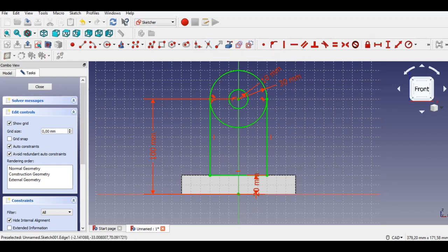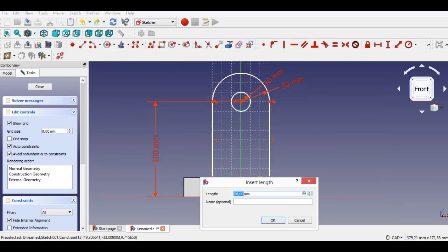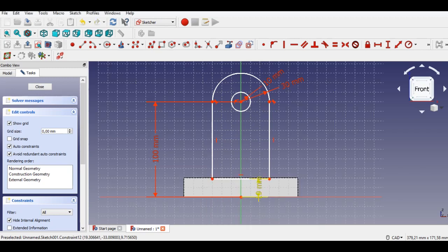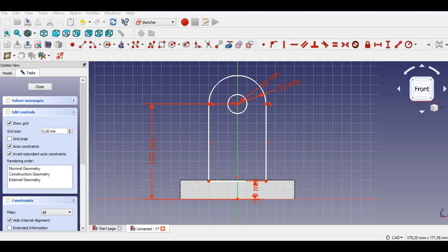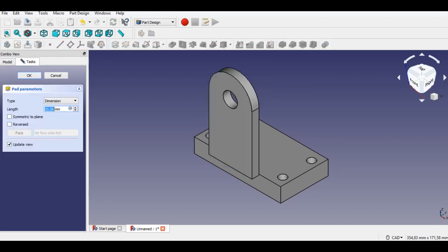We are making a 15 mm pad. We select this pad as reverse direction. Now we return to sketch to make the 3 mm part, and we select the corner side of the part and click the sketch button.